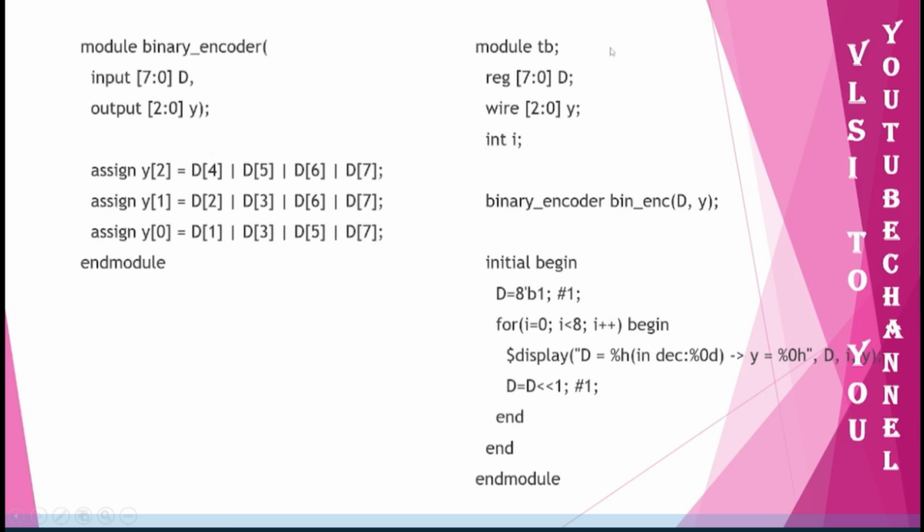Now since you are passing the values, again the same thing. For passing values also, you have just made the module instantiation, and here also you can reduce it like this. First, D is 8'b1. So the size of D is 8 bits, and it is a binary value, 8 bits, and its first value is 1.